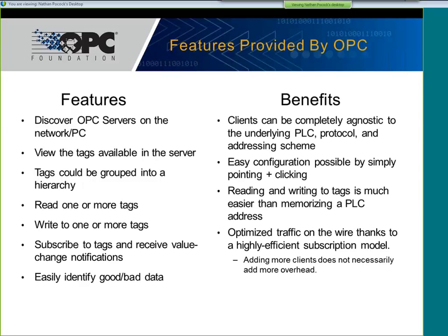So some of the benefits of adoption of OPC in this case were that the clients can now get out of the driver business. They could just have one driver, OPC. The configuration of the client would be much easier too, because now you can just use point and click. You don't have to memorize PLC memory addresses. You just work with tags. You can read and write tags quite easily instead of having to memorize these addresses. And like I said a moment ago, the optimization on the wire was pretty significant.